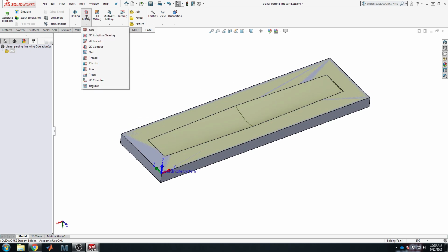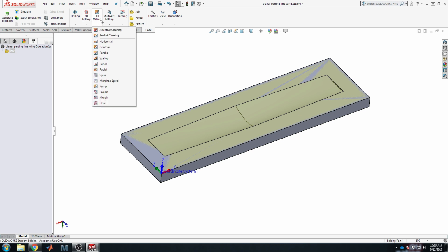2D milling is great for cutting out bulkheads, cutting out shapes out of maybe fiber reinforced plywoods. If you make some flat stock and you want to cut your airplane ribs or, like I said, bulkheads, longerons, motor mounts, etc. out of it, then really in 2D milling you'd go down here. I think 2D contour is the most useful tool process. But we don't have 2D molds today, so we're going to be going straight to 3D milling.